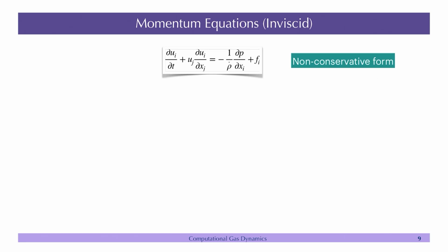So, my rho is appearing here, and this entire thing is the nonlinear term that we talked about, and this is the time derivative term. How to convert it to conservative? When I say I want to make it conservative, that means I want it to be in the form of rho ui. The rho can be absorbed in the new quantity, which we call the conserved variable. So, it can be rho u, rho v and rho w, and there are certain advantages of capturing them together, which we will see shortly.